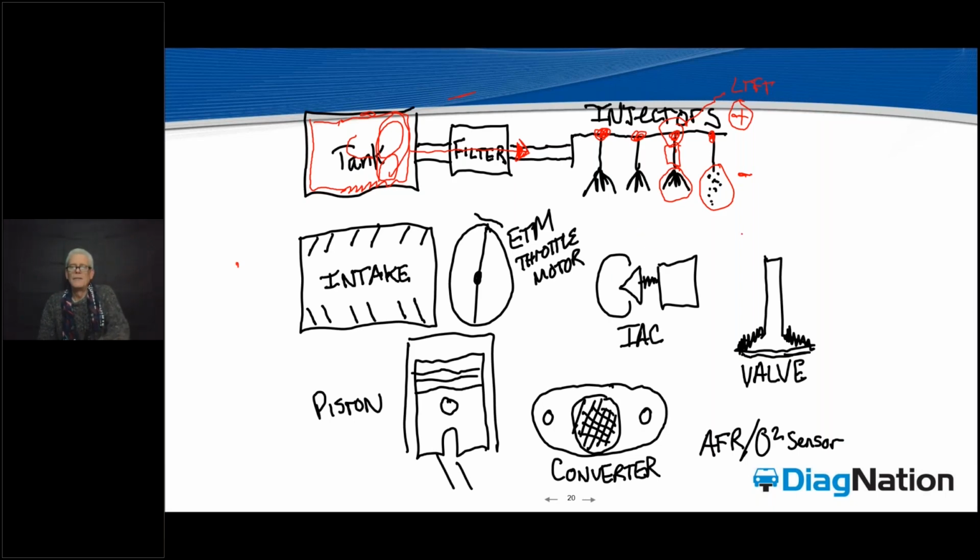Okay, now, let me see where I am. I can hardly see that dot. There we go. If we consider and move this deposit into the intake runners, and believe me, guys, if you've gone down in these intakes, especially the really bad ones, with a borescope, you know, not only are we getting that deposit on the valve, but worse than that, the intake runners are becoming infected with that carbon deposit, and it's growing on the intake runners right where the air charges down into the valve.